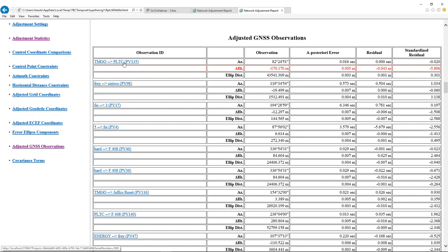You basically have to justify keeping it in there. So maybe you have to set up underneath some power lines, and you have very noisy GNSS data, and the conditions are just terrible for GPS, but you need to set up there in order to get a vector that's critical to your network to allow it to be adjusted. You may, in some instances, decide, I'm going to live with that particular observation, even though I know it's kind of noisy, because I need it to get the adjustment done. But in most cases, you're going to just throw away observations one at a time.